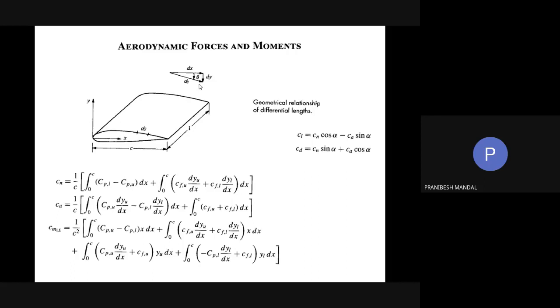If we actually test a small model of an airplane in a wind tunnel and get these particular force coefficients and moment coefficient, the same particulars we can actually use for the actual airplane also. Obviously, if other conditions are prevailing.